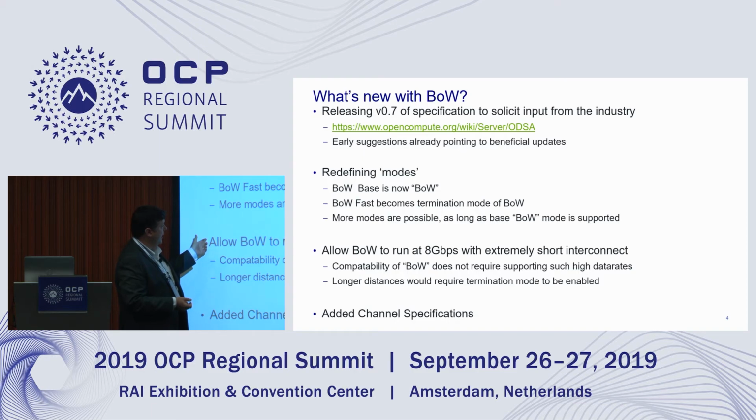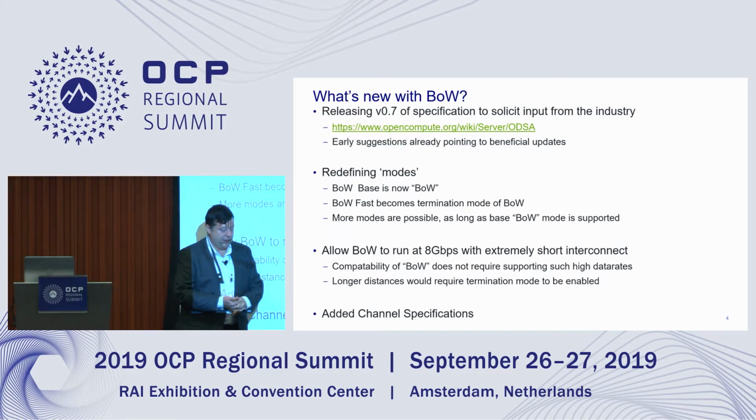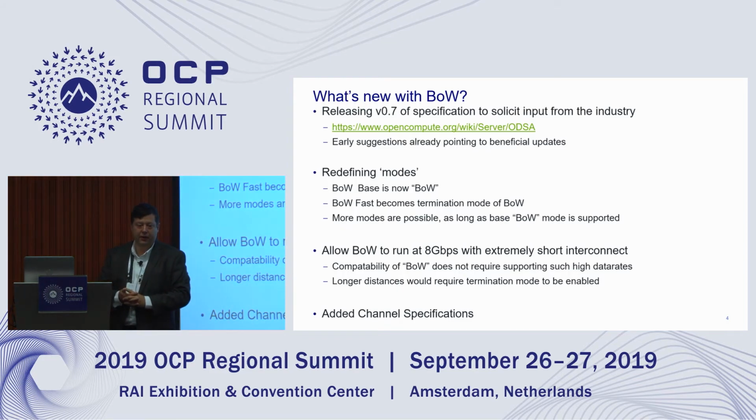We're looking at, again, in this base mode, we also slightly modified the definition and data rates to allow for a higher data rate connection up to 8 gigabits per second with extremely short interconnect, realizing that some really interesting advanced package technology is actually becoming cheaper and more available. And we wanted to make sure that we could support some higher data rates when folks use this advanced technology to have really short interconnect with really low power.